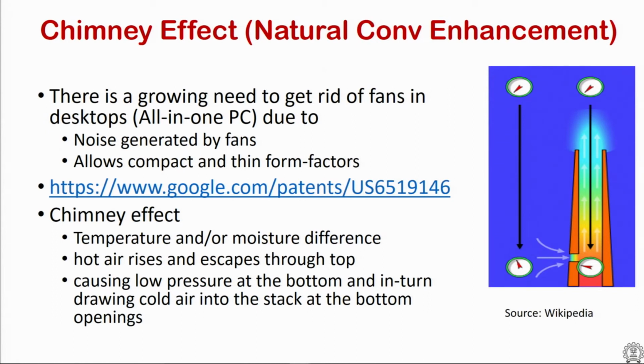So, the effect of a chimney, which is essentially providing a long draft on top of where the heat generation happens, is that it increases the natural convective velocities much more than without the chimney. So, chimneys do in a way enhance heat transfer by increasing the velocity, though not necessarily by directly increasing the heat transfer rate. By increasing the velocity within the natural convective zone, it improves the heat transfer indirectly.